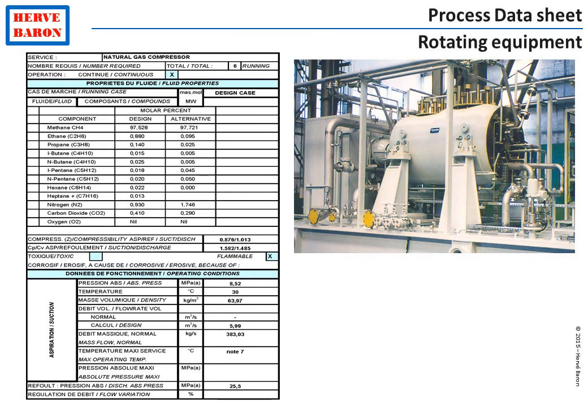The datasheet of equipment which are not designed, which are not sized by process, but merely specified, such as rotating equipment, heat exchangers, fired equipment, primarily indicates the inlet and outlet stream conditions. They also provide all information necessary for the vendor to perform its design.